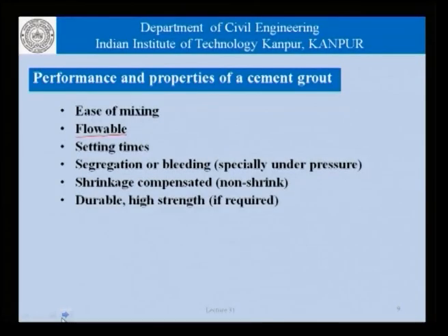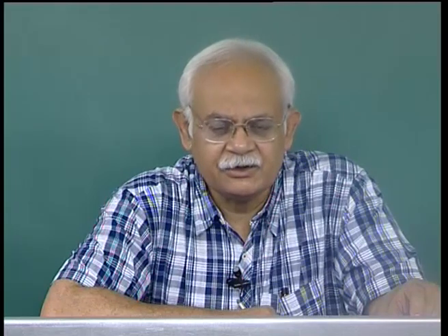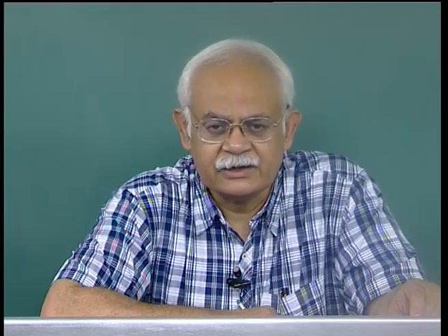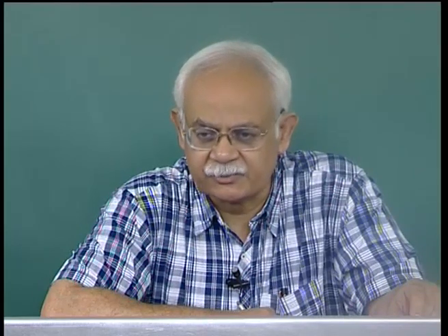Durability and strength are obvious requirements in any cement based construction, and grouting in post tension concrete ducts is no exception. We need or we may need to specify that the grout that we use attains a certain strength at a certain point in time, whether it is 28 days or 7 days or 3 days or whatever the time be.